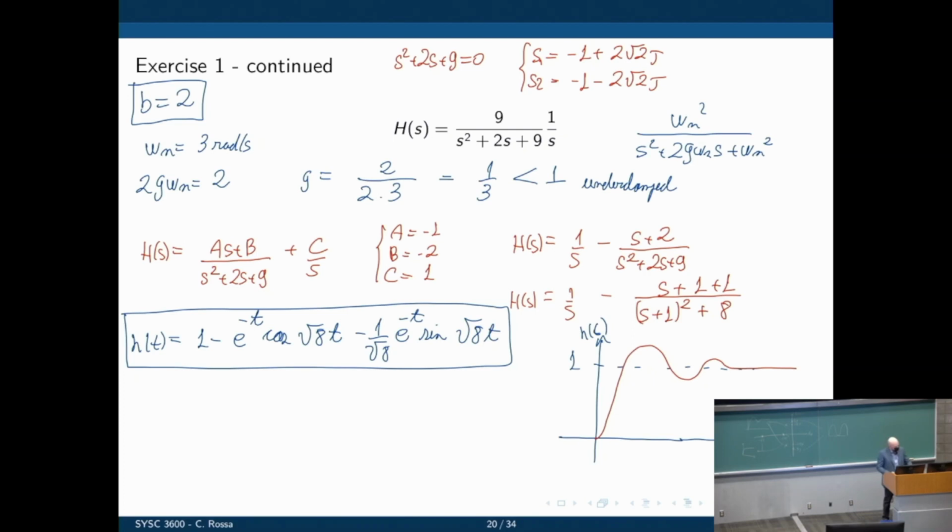The last example is for b equals 6. And when b equals 6, we'll have a critically damped system. For a critically damped system, we'll see the two poles at the same point, and then we shall see also an exponential waveform as a result of that. I will post a solution for that one later. We'll just add another point to our graph here, around 3, 2 poles at the same location, and then you still get that waveform.